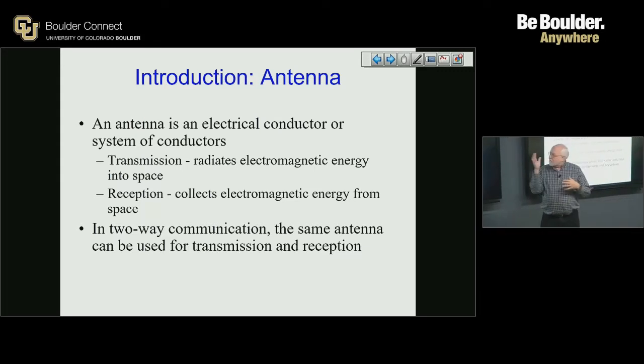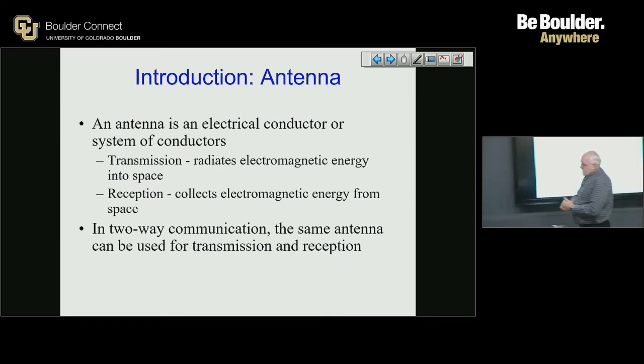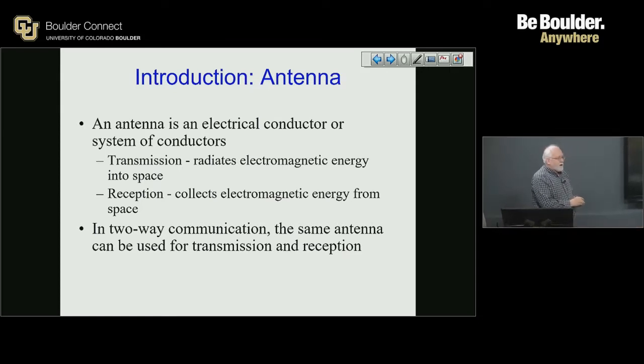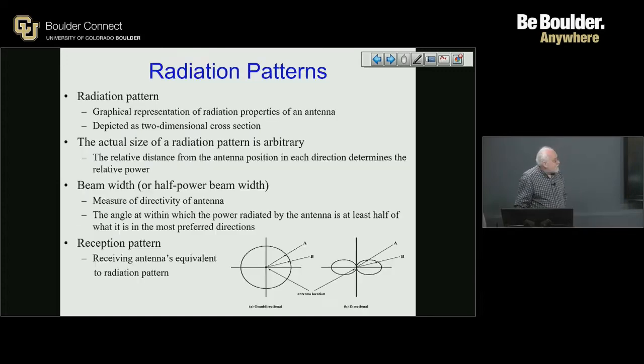Antennas have properties, and we'll go through this in more detail, but antennas have properties of gain, that they can have directional gain, so there's more gain in one direction than others. And in more modern Wi-Fi systems now, we do what is called beamforming, where we can take multiple antennas and change the phase of the signal going to those antennas and steer the energy in certain directions. So it's used, in fact, in our latest version of 802.11, where we can accommodate up to 8 antennas, and we can use the 8 antennas either for MIMO or for beamforming.